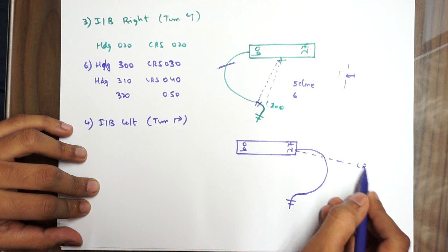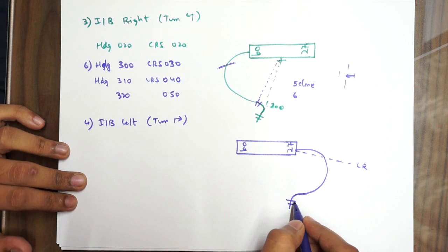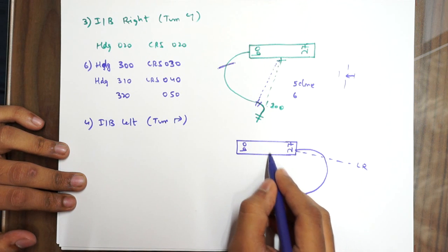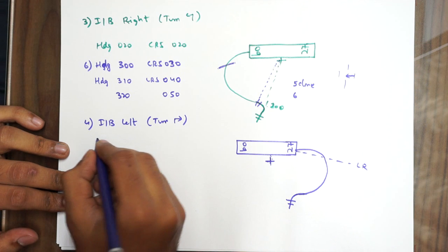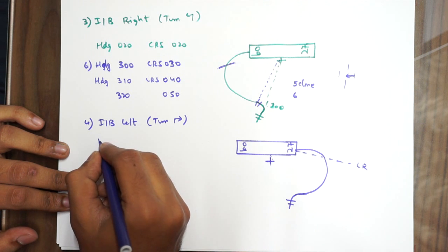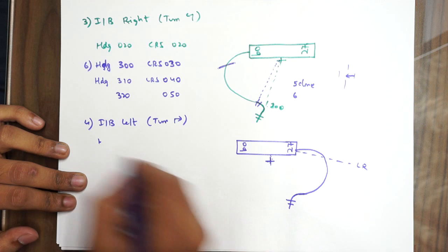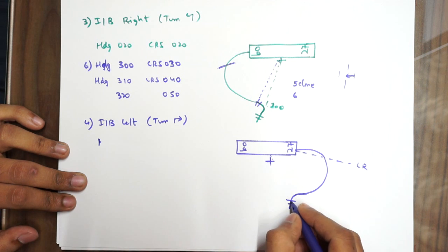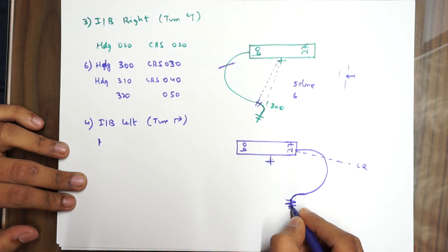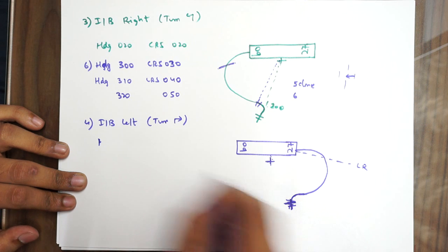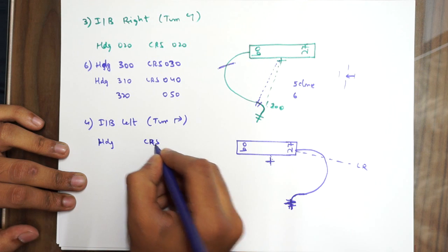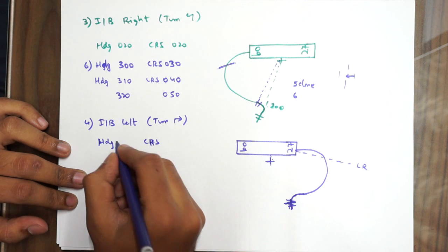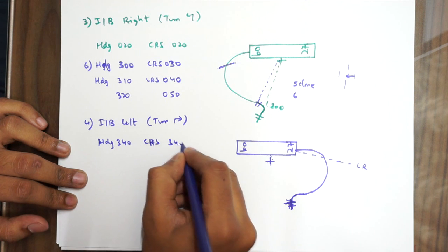this is the lead radial. Okay, so let's for example, let me just put it here, the VOR. So let this be around about 160. All right, so at this point in time, suppose you will come in like this, right? So let's make the aircraft like this. You're coming in perfectly on heading and course. Okay, so your heading and course will be 340, 340.